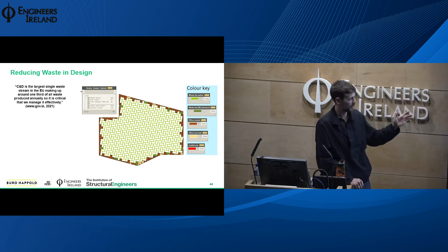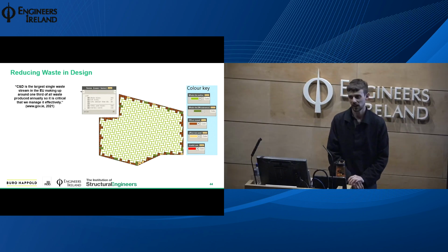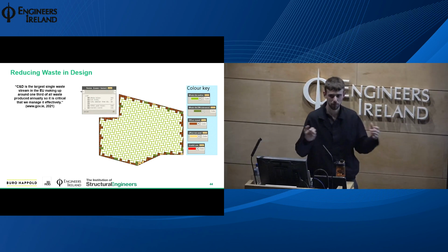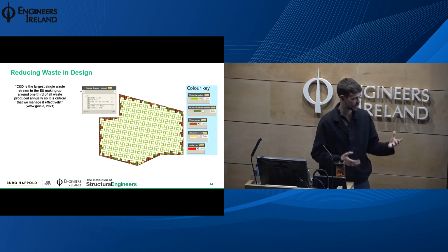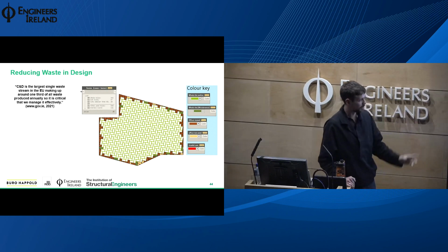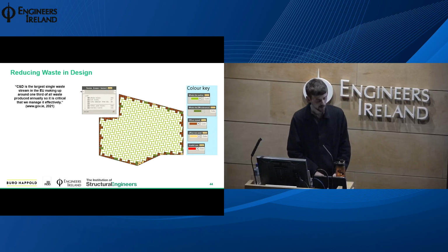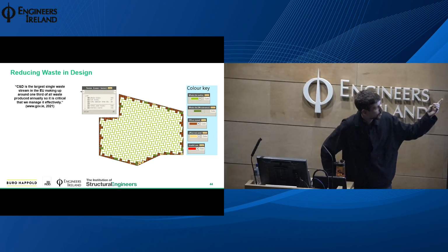This might be a wacky patio or something, but structurally, if you have a massive floor plate with a few weird angles and you've got a precast plank solution, you want to try and lay those out in the most efficient way, which is going to reduce the weird shapes or the special objects or any cuts that they might have to do. So you can then just quantify the number of components within that.